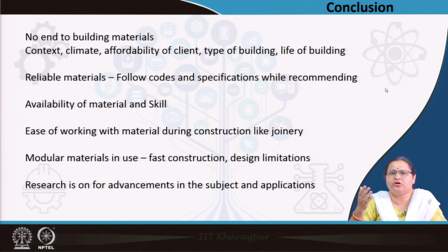Material should be reliable, it should be available, and the skill should be available. That is why our country could not move to the faster construction methods of precast items, though they have limitations, but we at times require fast construction. So, we have to understand what is the purpose of the building, and we have to find whether these materials are code specified before recommending it.